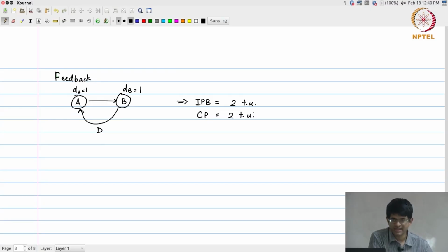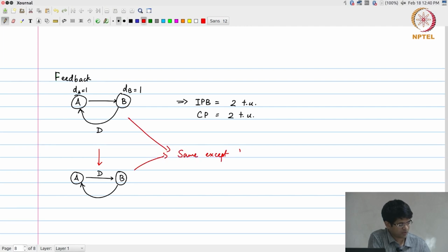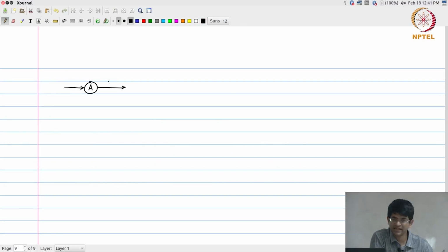Now, even though this has already hit the critical path, there is one thing that we can observe from this which is useful to understand, which is that the two graphs that I have drawn over here are essentially the same except for the delay unit. And what we can essentially say over here is that one is a so-called retimed version of the other.